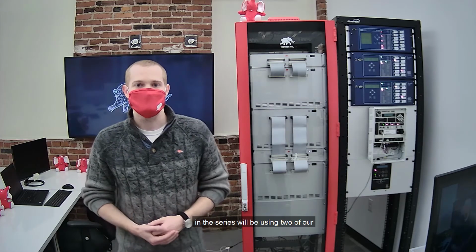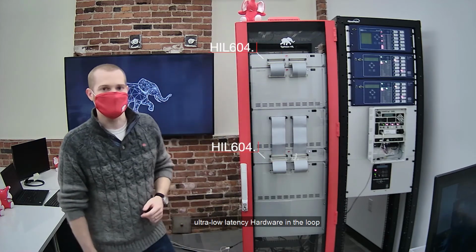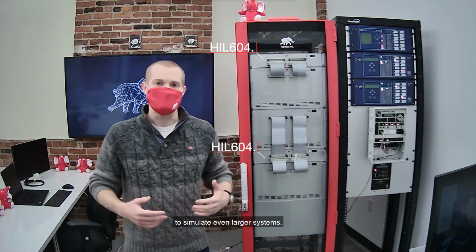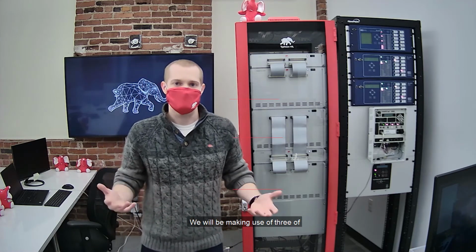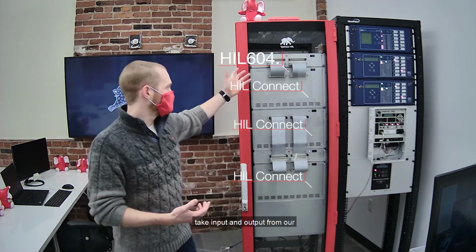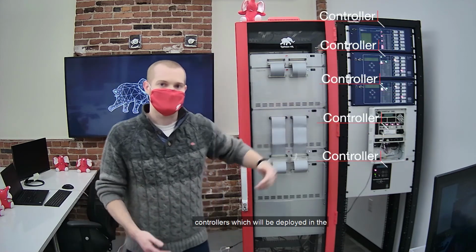For the series, we'll be using two of our Hill 604 ultra-low latency hardware-in-the-loop simulators. These on their own are an industrial workhorse, or they can be parallelized to simulate even larger systems. We'll be making use of three of our modular Hill Connects. These Hill Connects act as signal conditioning. They take input and output from our Hill simulators and actual hardware controllers, which will be deployed in the field.